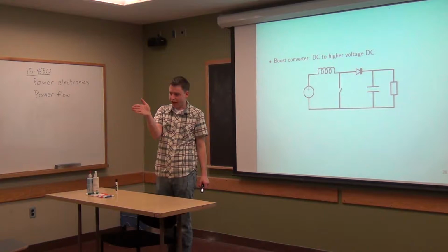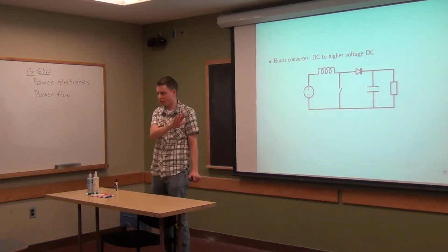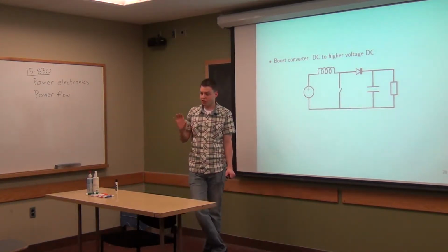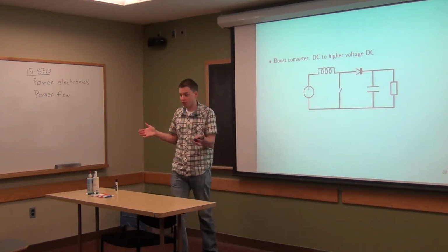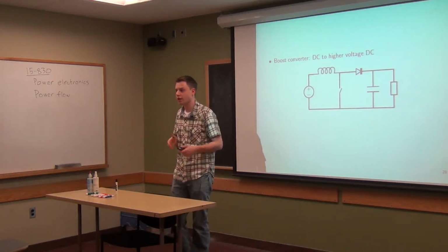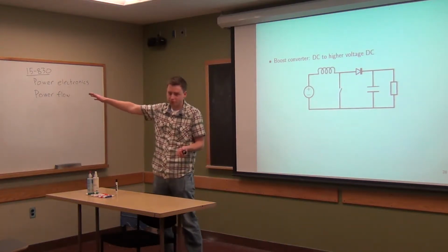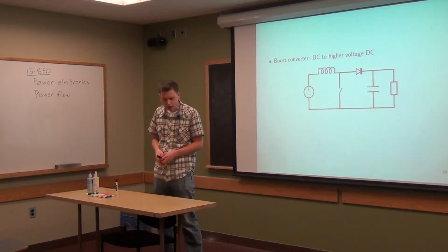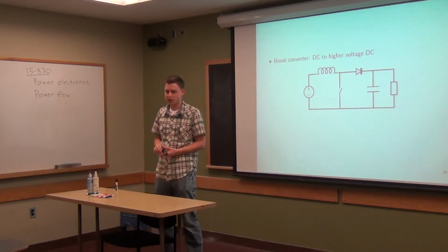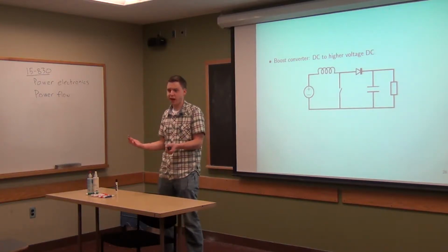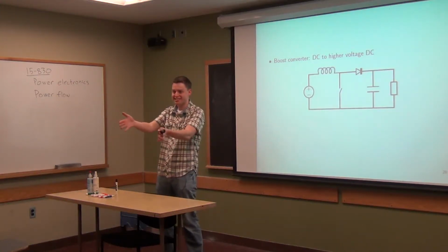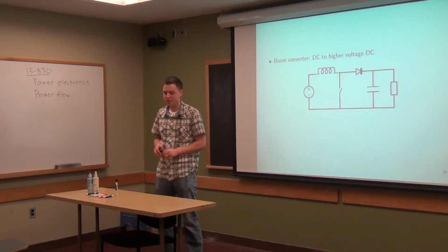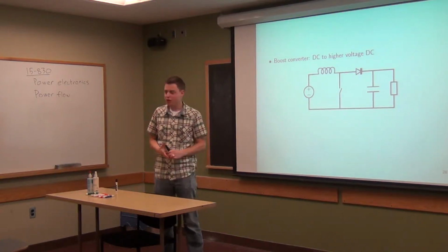But the end of the story is that because of these effects, whatever they are, people often tend to favor DC power for long underwater cables. And as these become more prevalent, say with offshore wind farms and wanting to transmit power to islands, for example, we may want to use more and more DC power. There also are some other really big advantages, just the fact that there are not these issues of reactive power losses. We don't have to worry about reactive power because it's just DC power. There is no reactive power. That's an advantage too.